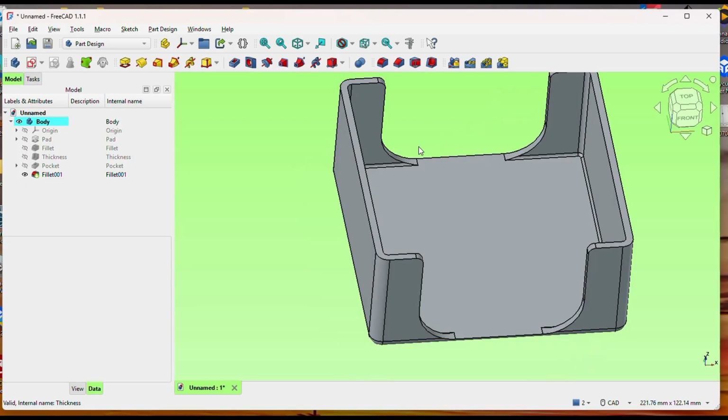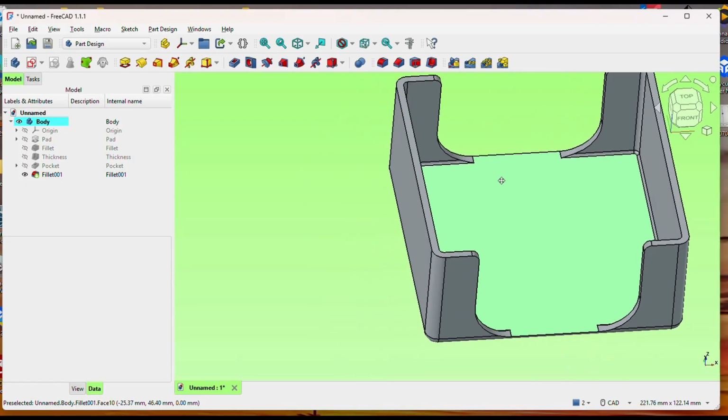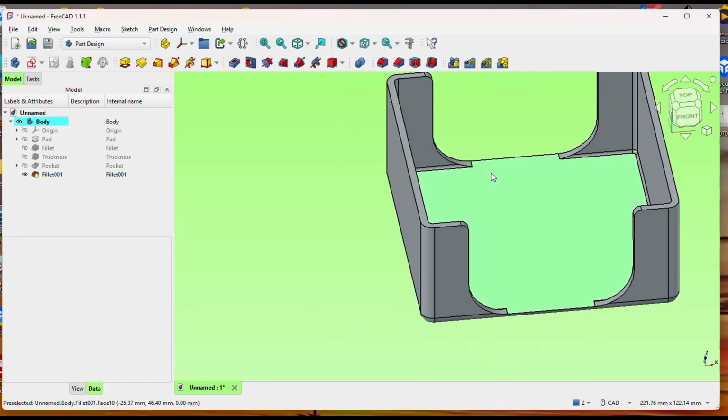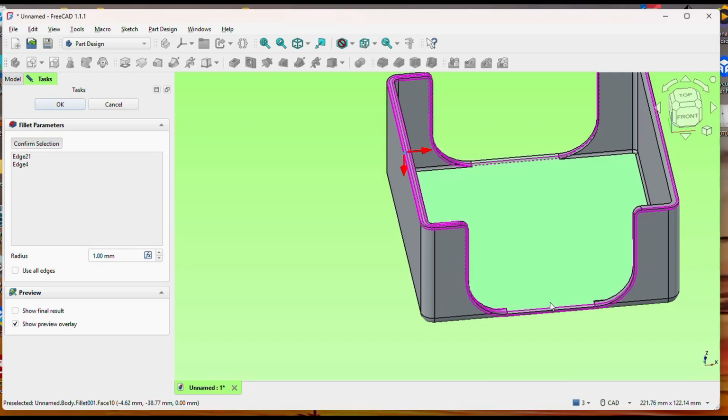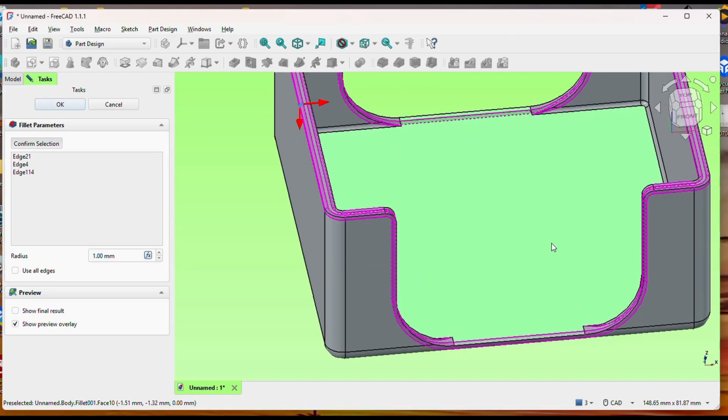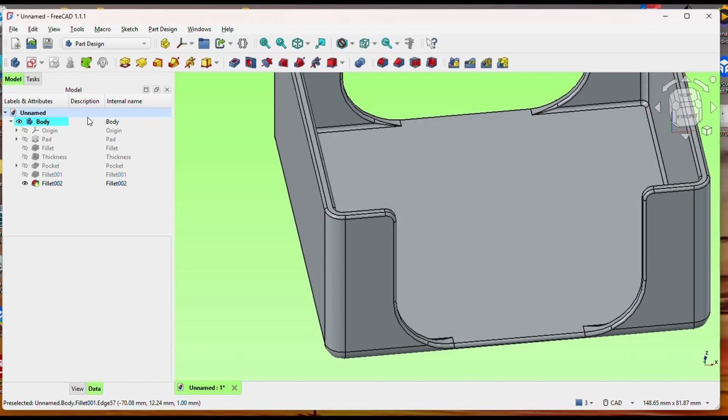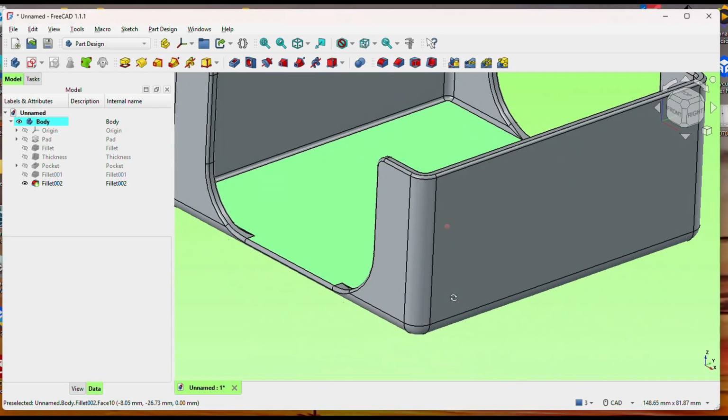And it's still got some sharp edges up here. I'm going to 3D print it. Rounded edges or chamfers work better. So let's go here. Do a fillet again. Select this edge. That goes all the way around. I'm going to select that edge. That goes down to here and that edge. And that's a little bit too much for me. So I'm going to go a 0.75. Say OK. And there you go, a nice rounded edge.